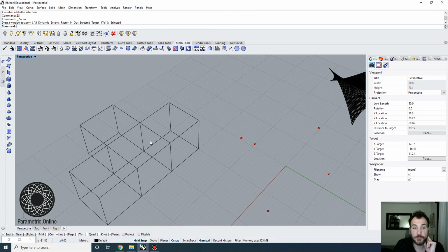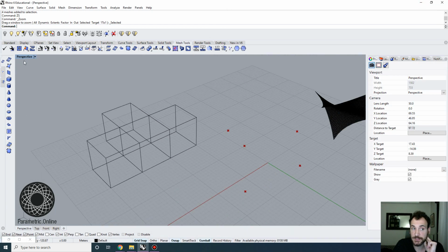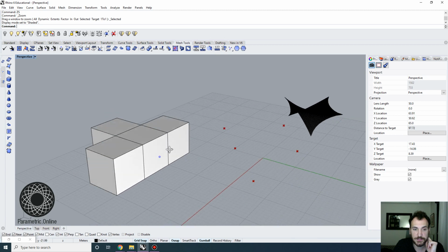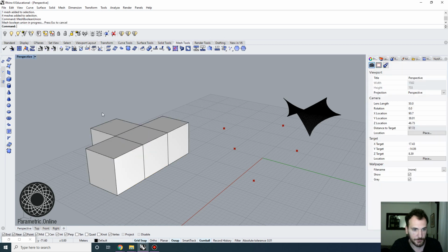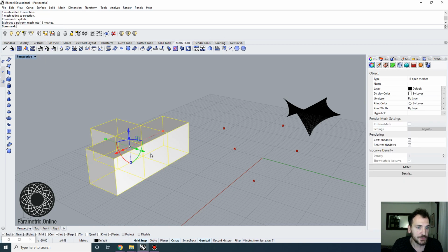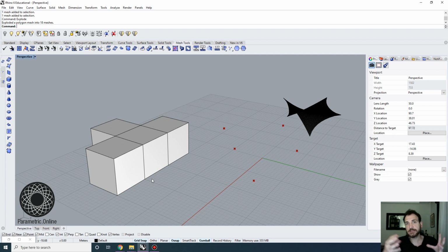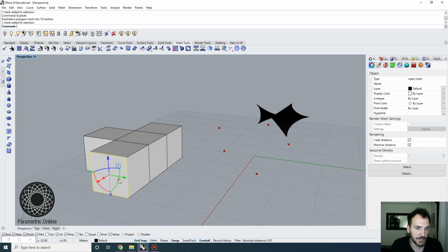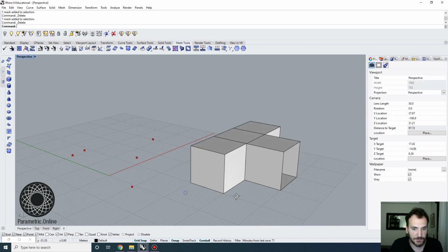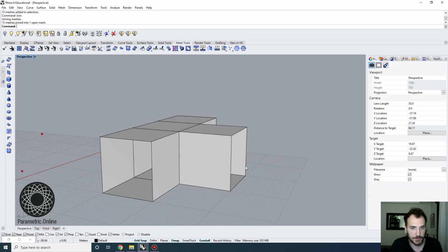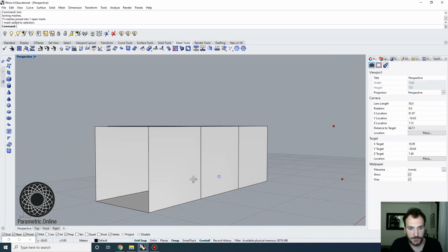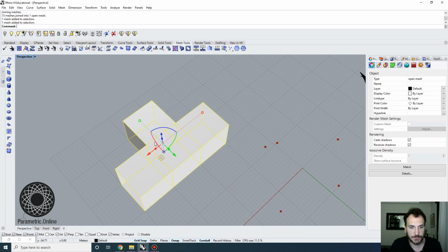And remember that we are working with meshes, so these vertices need to be snapping to each other. So that's the essential part. And now they're distinct. But you can select all of them and do mesh Boolean union. And now these are joined. So I'm going to create a relaxed form, like a net in which we can go through, right? So this is going to be a volumetric relaxation exercise almost. So I'm going to delete these faces, and the remaining faces I'm going to join them. So imagine that this is a tunnel where we can enter, and we will have 2 different exits, right?